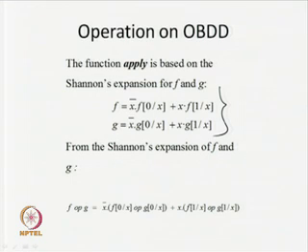These are the two Shannon expansions of our given functions. Now, if we are going to perform any operation f op g, you just see that we can rearrange this expansion. We have x bar, then we perform that operation on the evaluation of function f replacing x by 0 and the evaluation of function g replacing x by 0. We can perform this operation on these sub functions, because we have already taken the decision of x equal to 0.